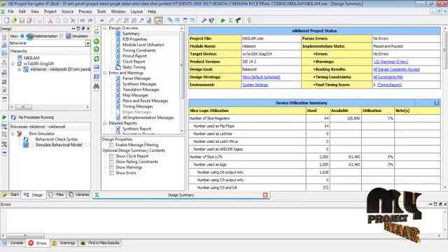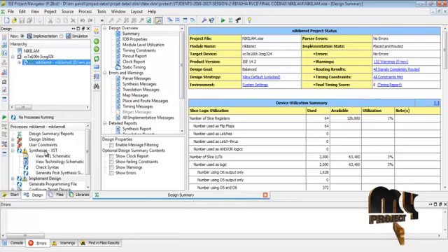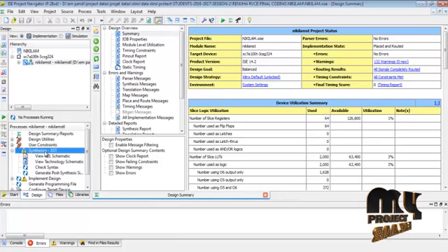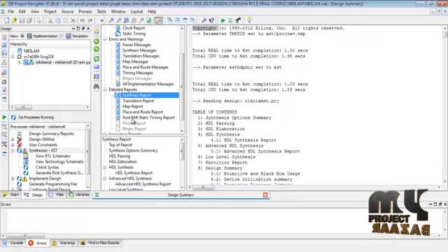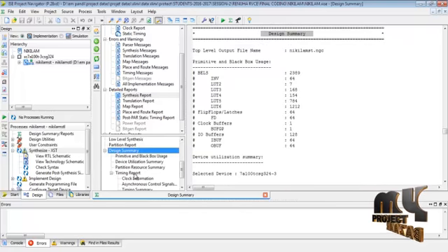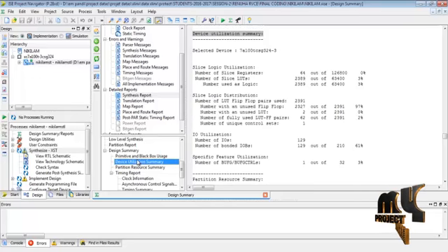The next one is the implementation design. In the implementation design, first we click the synthesis XST, and then it starts to run. After it runs, we click the implementation design, and then the corresponding output will be shown. In the synthesis XST, we can see various kinds of output. The first one is the synthesis report, which has the design summary and design utilization summary. In the design utilization summary, we see how many LUTs we used, how many slice registers we used, and how many bonded input outputs we used. That utilization is shown in that block.